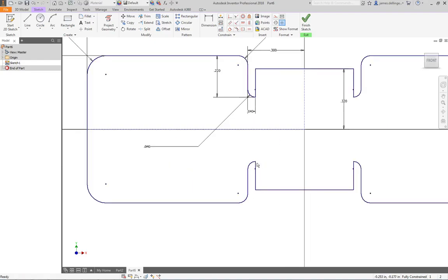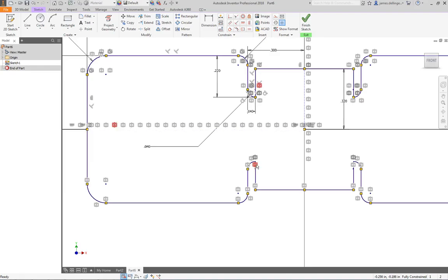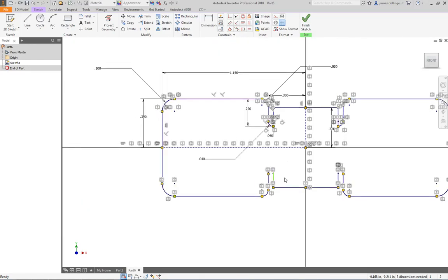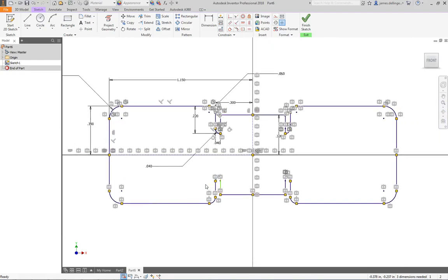This should, all right, and it's the mirror command. So if we want to debug this, you can go in, turn these on, and say, you know what? I know I've mirrored this. It should be fine, but this is not working because of that mirror constraint, and so I can delete those mirror constraints on that point. All right, it just gets to be a giant hassle for you guys. All right, and this is supposed to be practice for mirror.